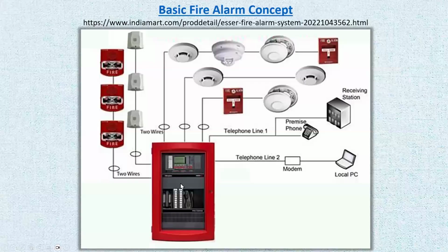And the person who's standing there, the resetter, has some communications, it could be walkie-talkies, it could be cell phone, and constant communication. Okay, I've triggered a device. What does it show on the panel? Yeah, it shows east hallway smoke or something like that. Okay, press the reset button, and then I'm going to trigger the next device, and so on and so on.